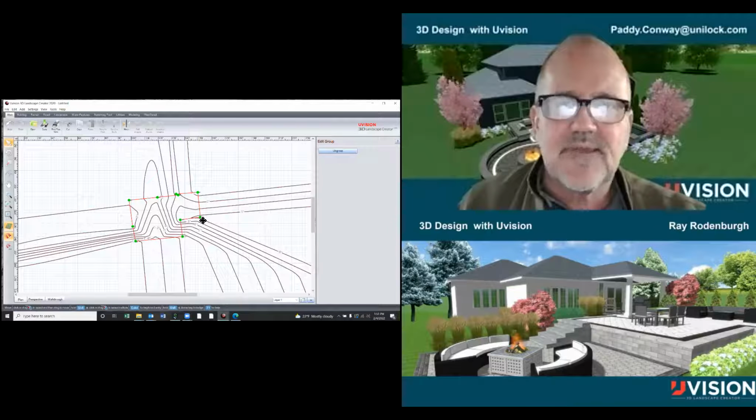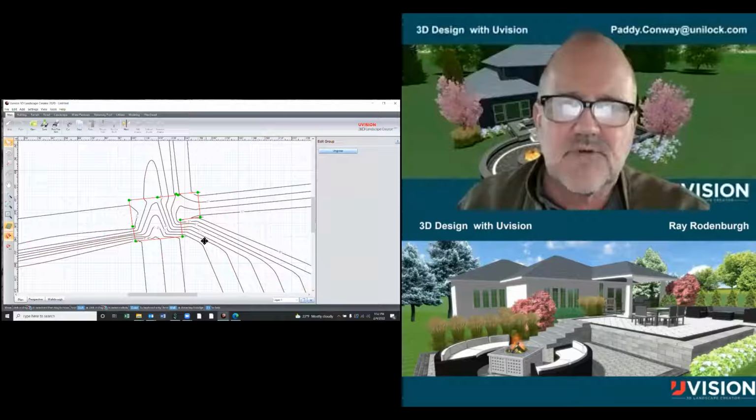As you import it, it'll say what increments do you want. 3 inches is tighter than a foot, 2 foot, 3 foot. So in this example, I came in at 3 inches. It's going to give me more lines. If I said every 12 inches, I would get 1 in 4 of these readings on the screen here. So that's what the increments are, and you can see all my stations.